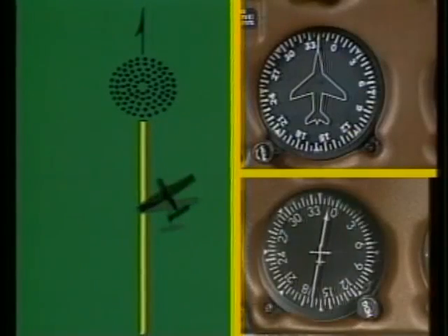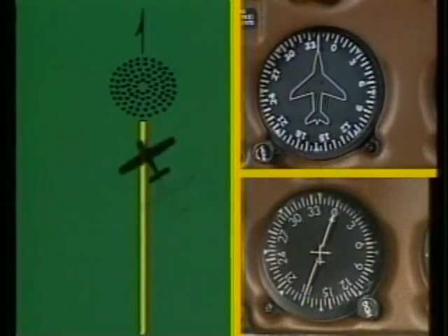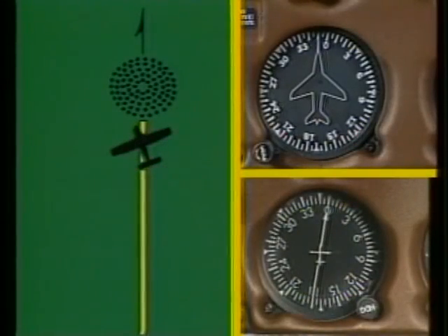So, an additional correction is needed. In this case, you are using a 20-degree correction angle to regain the course. If you continue to keep the ADF heading aligned with your magnetic compass, you can verify that you have returned to the course when the head of the bearing pointer equals 360 degrees. To remain on course, use just enough crab to maintain this magnetic bearing.